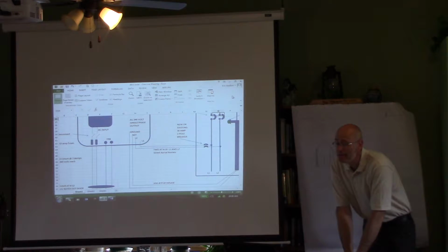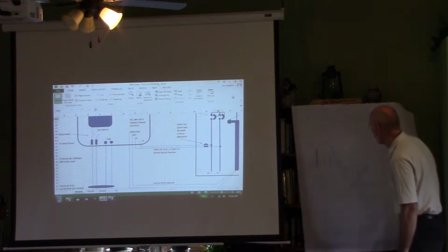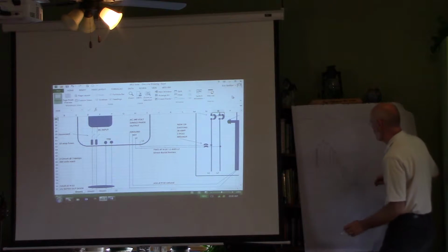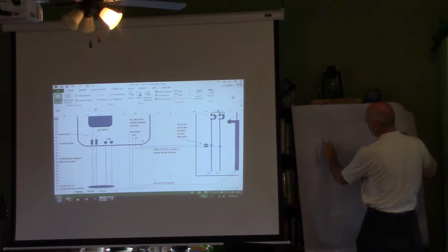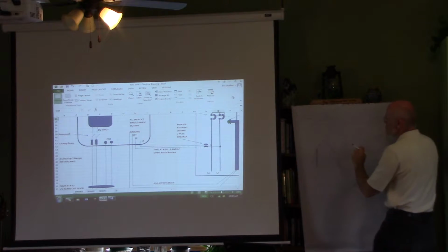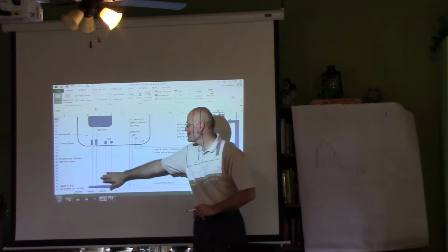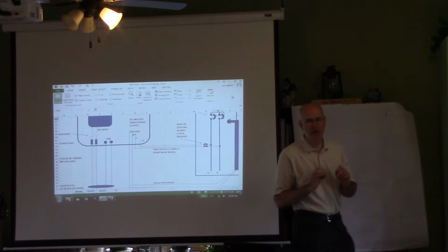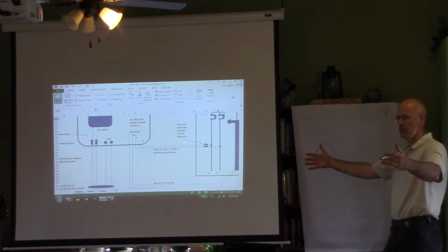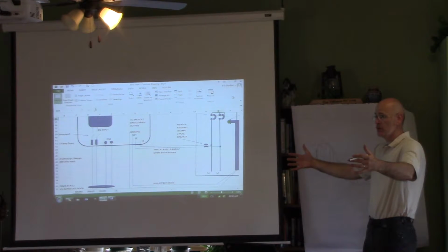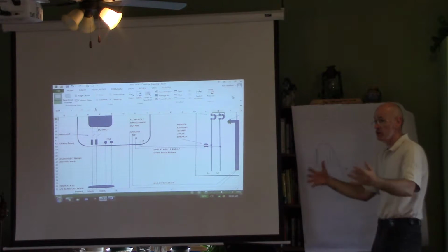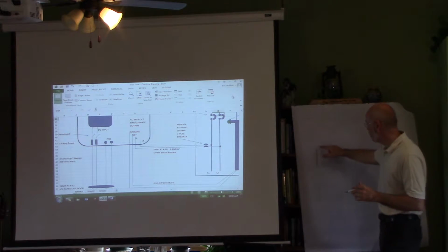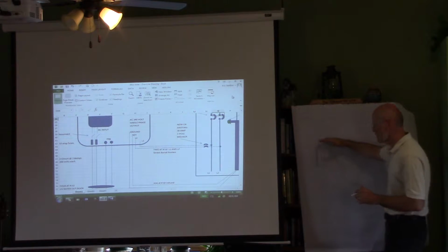So Dave, when the solar panels are really cranking out at high noon, those pulses get even higher then? No, it's just stronger than the utility, just enough above it, so that all of the amperage, the 15 amps coming in here, is used. Another way of looking at it is, you've got that big bathtub of water, which is the capacitors. They don't want those to overflow. If they get too high, it'll shut down. So it's going to drain those capacitors in that split second. It'll push this high enough so that it gets used up.